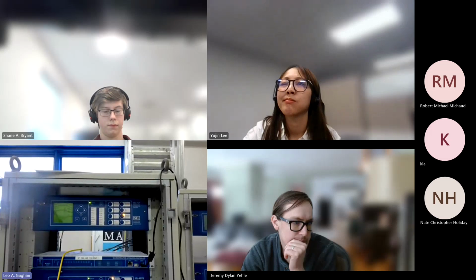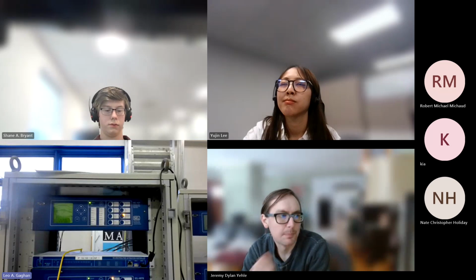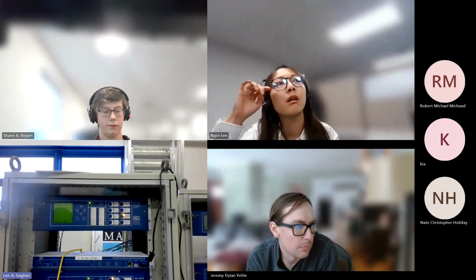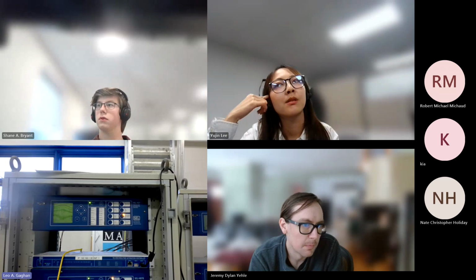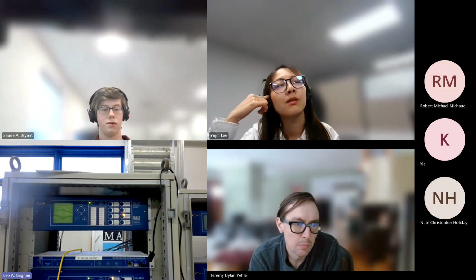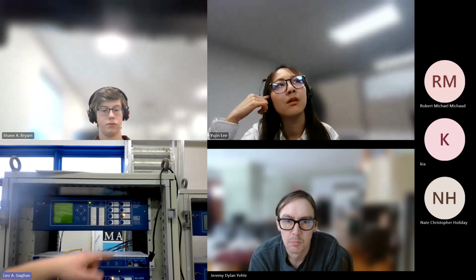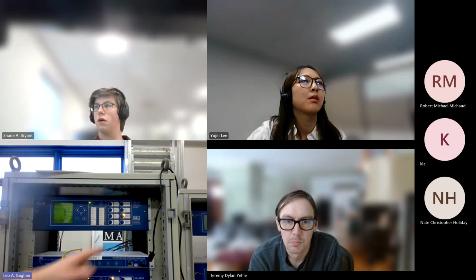So we'll start with the beginning of this logic here. It looks like maybe the first thing on here is the push button for the 52 control switch of the breaker or the relay. What we've got on here is a push button for breaker closed and breaker open. Right now we can see that the breaker is closed.